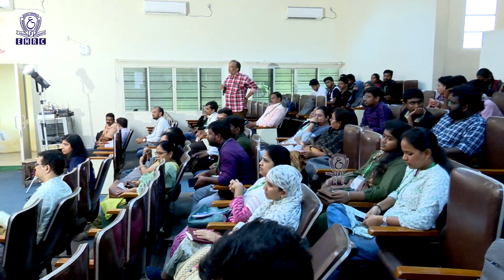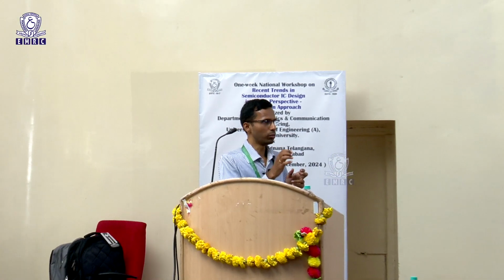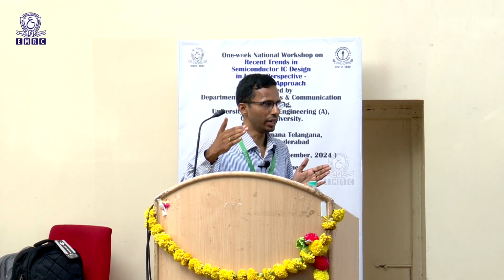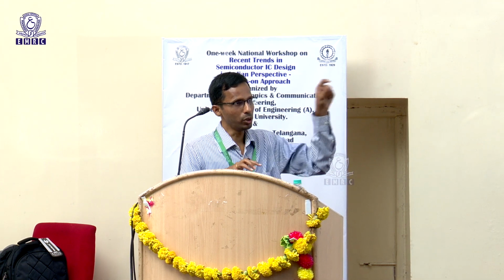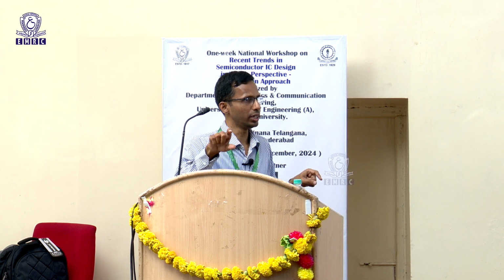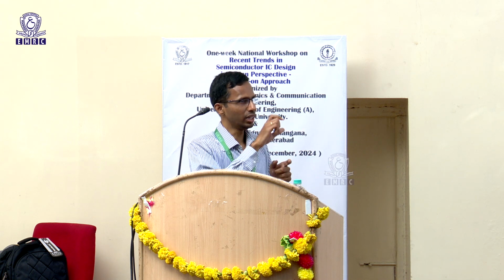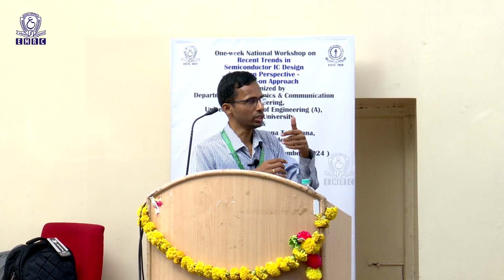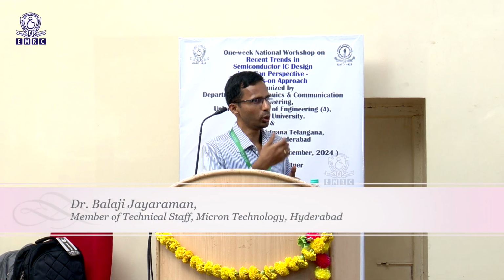So the data path: once you fetch the data from your DRAM cell, you need to take it through the sense amplifier, which is a mixed-signal block, and then once it comes out of that block, it has to reach your DQ driver. The DQ driver is again going to be analog, but this path all the way from your sense amplifier till it reaches that DQ block, wherein you go from one bank to the other, is digital. If you are doing a read operation, you need parallel to serial conversion, and you also need to have a FIFO.